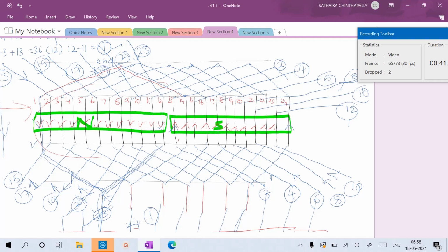You know the winding table, you know the winding diagram. Simply draw the ring diagram as the question is asking. Locate the brush positions where in a coil both directions are the same. Then mark the brush as positive where the current directions are downwards under the north pole. Mark the brushes as negative where the current directions are upward. These are a few points you have to remember, dear students.